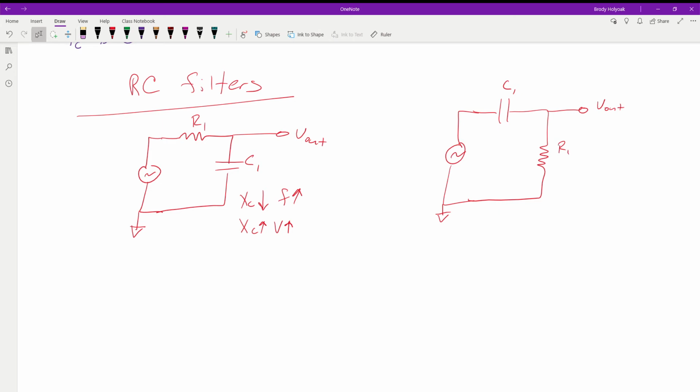So here we have a 15 kilo ohm resistor on both sides, and we have a 179 picofarad capacitor. So using this information, we're going to sweep the frequency, calculate at several different points, and then find out at the very end what our critical frequency is, and what type of filter this is.